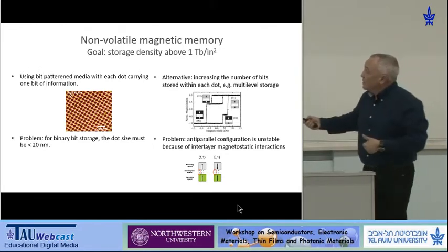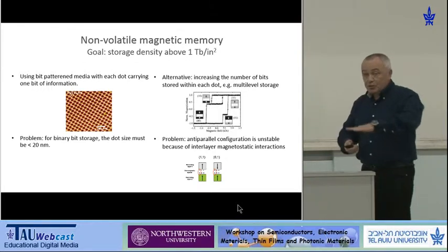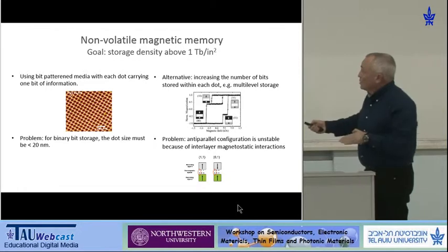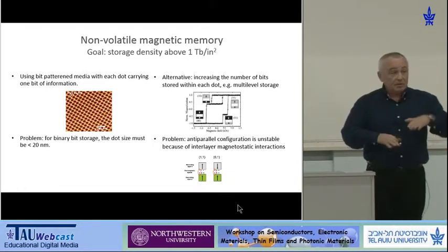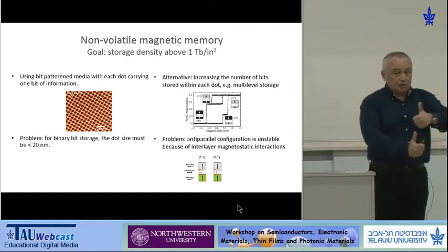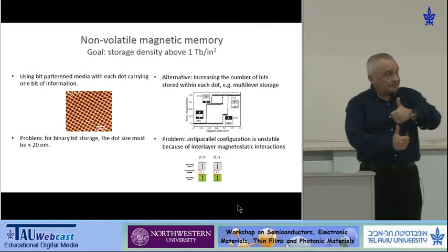Another way is to go upward and to do 3-dimensional memory. For example, by making what you see here, which is just the magnetic film, which is in fact 2-level magnetic film. So one with perpendicular anisotropy and the second one with perpendicular anisotropy, and that's why we have in fact 2 layers or 2 bits, one on top of the second.